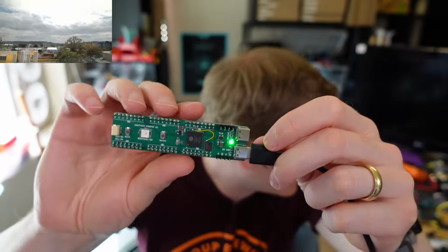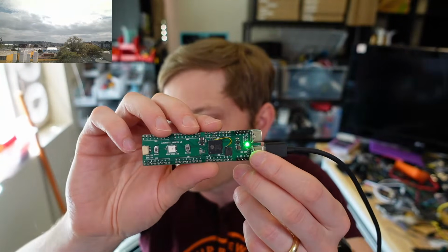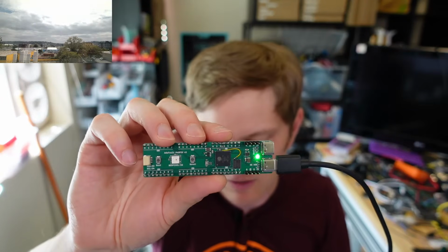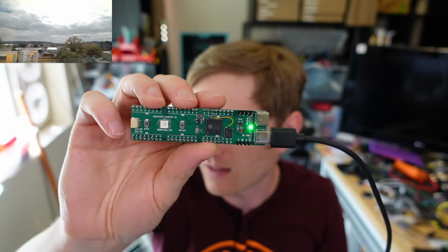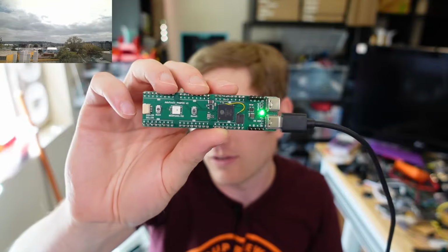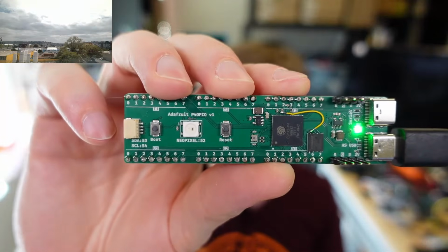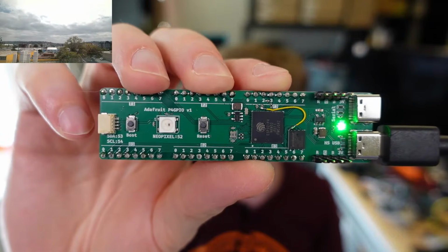The only other thing that I realized, well, one, I think the green LED is too bright, so I'm upping the resistor value for that. Right now it's 2.2K, and I think in the next version I'll do 5.1K, which is the same value that I'm using on the USB lines. Actually, I can hold it closer. Giant picture of that. So that's version 1.